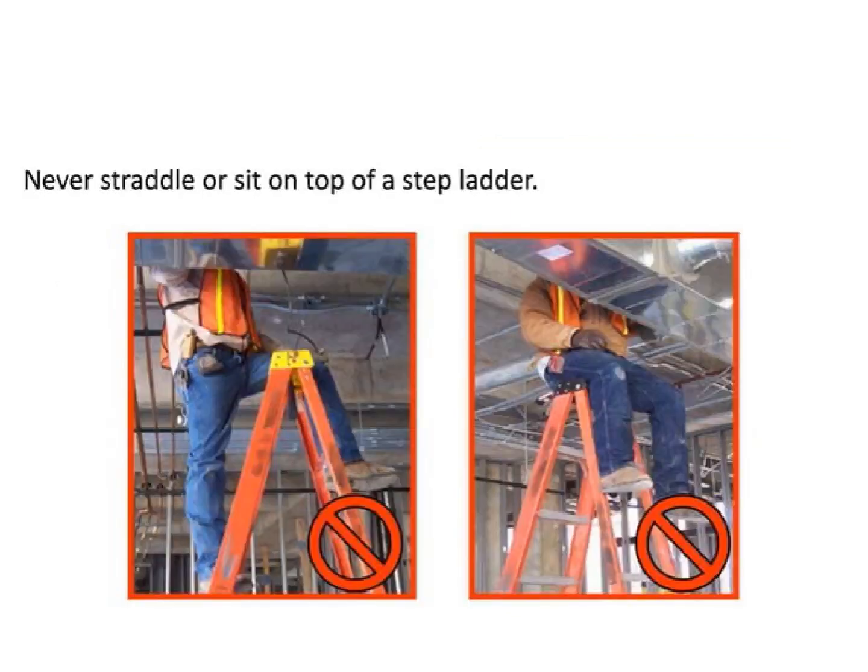When using step ladders, it is essential to ensure that you do not straddle or sit on top of them. Doing so will affect the ladder's stability and can cause you to lose your balance, potentially leading to injury. To prevent such an occurrence, always keep both feet on one step of the ladder.